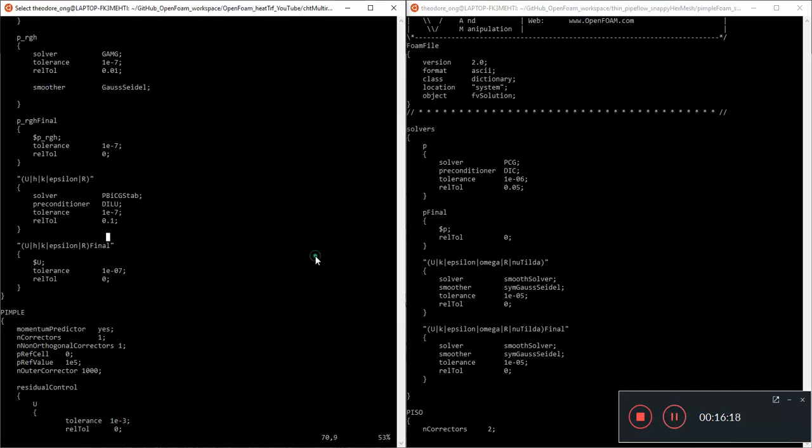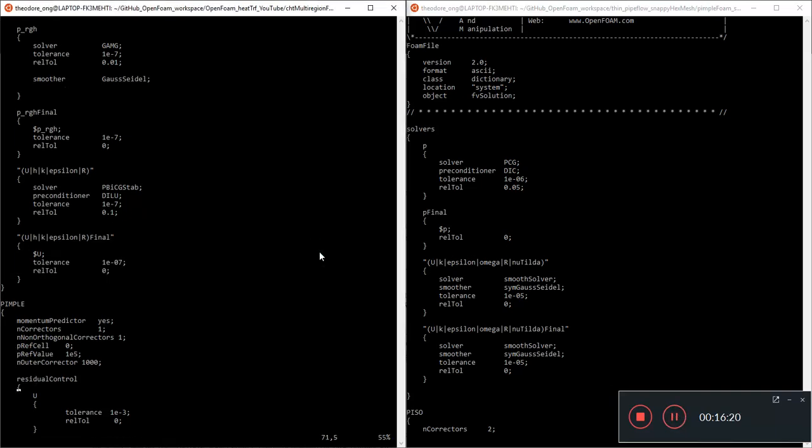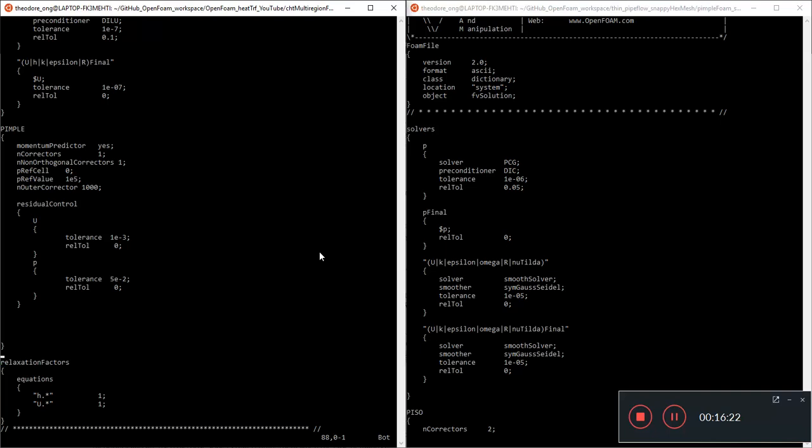Now, of course, all these things are useful to know. We can tweak these things later on, maybe in future iterations, but now let's just focus on the residual control first. So let's do an H field tolerance control. So H. Now, of course, if something goes wrong, we'll know where to take a look. So first thing, I want a tolerance.